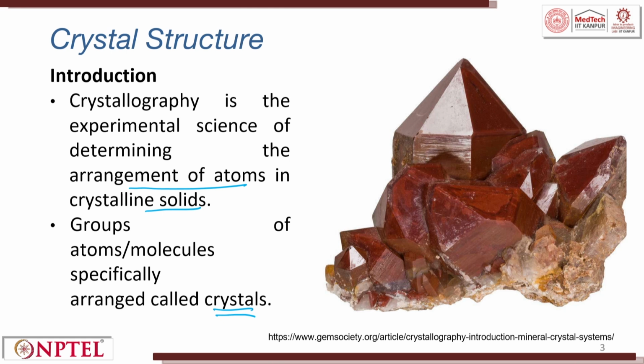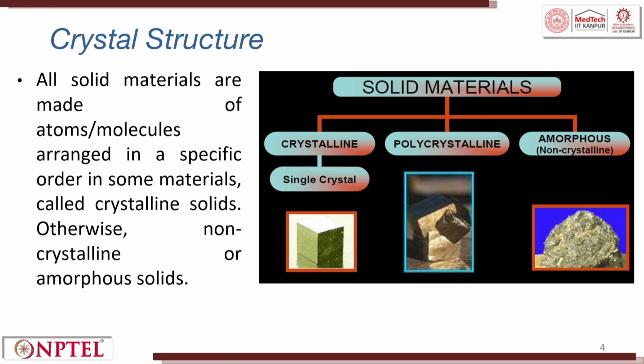This is an area which is coming up in a big way, because we are trying to look at exotic materials which have combinational properties, or we have hit the limits of various materials. So, now we are trying to dope with some atoms so that the crystal structure can be modified a little bit. When we take any solid material, it is classified as crystalline, polycrystalline and amorphous. Crystalline means it's a single crystal. Today, we talk about single crystal titanium material for turbine blade applications because of their excellent mechanical properties.